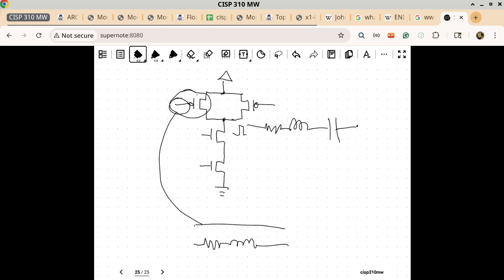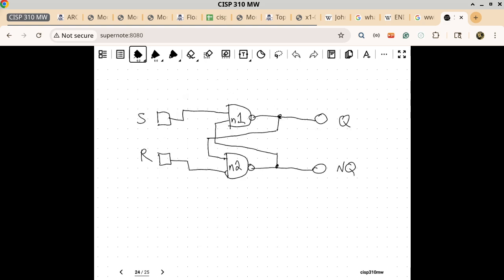But to us, we'll just say that, yeah, that's a delay. We simplify things to just the logical level. It's going to take some time, and that's all we need. So going back to this picture, the moment you make a change to any one of the two inputs, it's going to take a while before the output of the NAND gates changes accordingly. That amount of time is called the propagational delay, a term that is very important every time we deal with anything electronic.